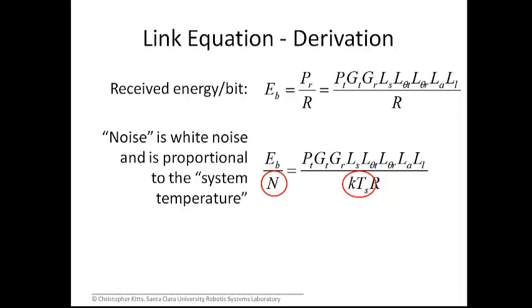But at this point, I have my full expression for the purposes of this lecture, and recall my comment about how you may or may not add additional terms or even remove some of the ones that are here depending upon your particular situation. So for example, if you have two antennae that are pointed mechanically to each other and they're installed that way, or if you have omnidirectional antenna, you might drop the gains. I mean, presumably the gain is still in there, it might just simply be a 1. But it's up to you to figure out how to wield the power of this equation.